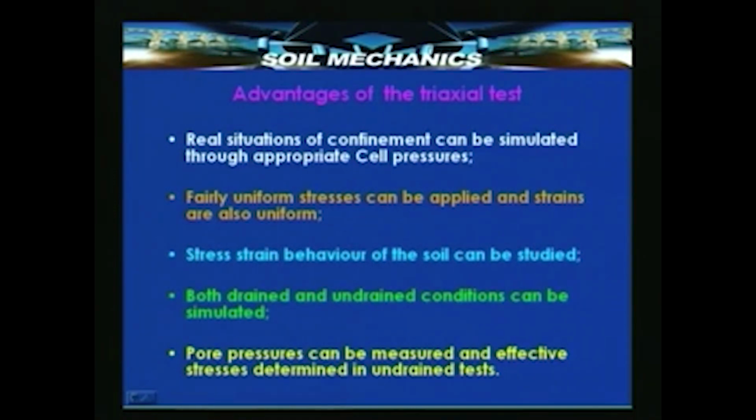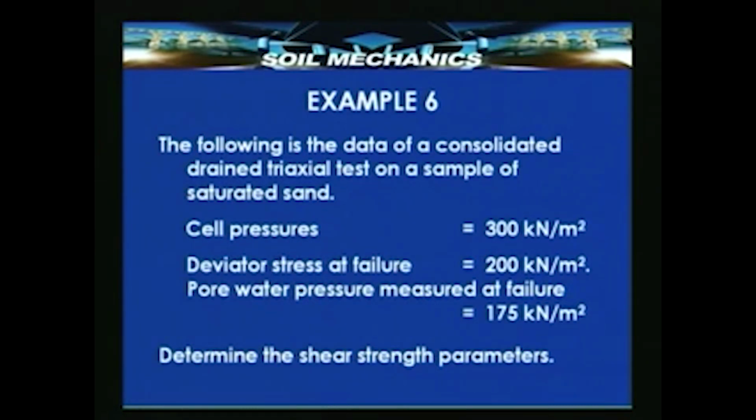This is a tremendous advantage, because the knowledge of the pore pressure tells us exactly what kind of effective stresses are mobilized during the test, and the shear strength is a direct function of the effective stress. Therefore, knowledge of the effective stress is very necessary, and the triaxial equipment can really help you to get that. Let us quickly take a look at some examples.